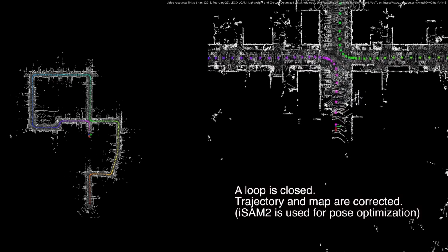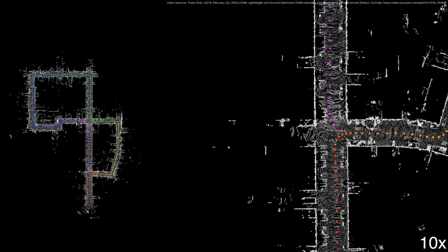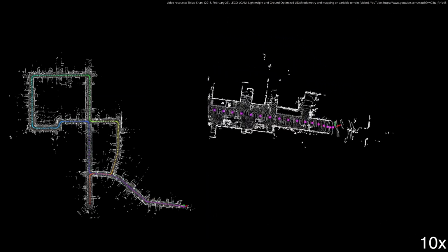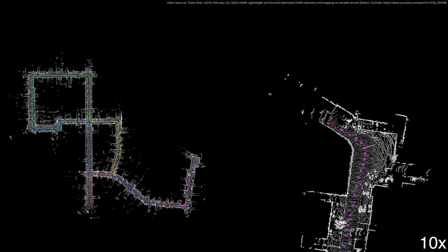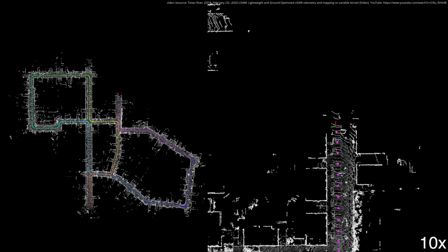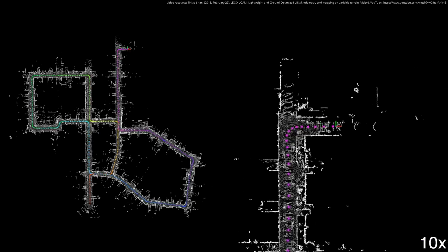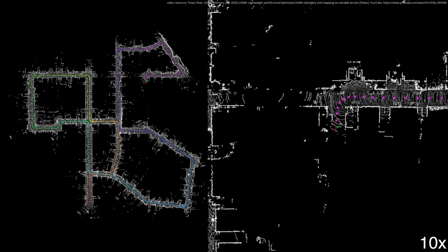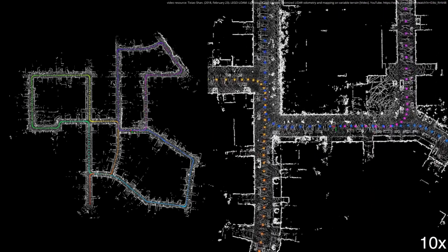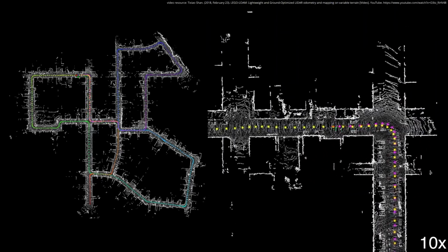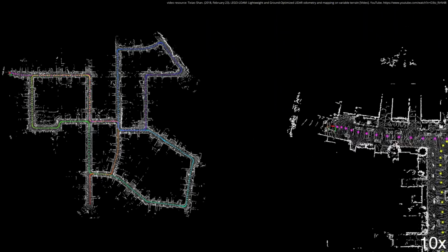Every time the robot reaches a location it already visited, a loop closure is detected and the estimated poses and therefore the map are corrected accordingly. Especially while traveling long paths, the SLAM algorithm with loop closure is a good way to minimize the pose drift and correct probable errors afterwards. In LoAM, no loop closure functionality is implemented because of its constrained performance. The processing speed is not high enough to provide SLAM with loop closure in real time.